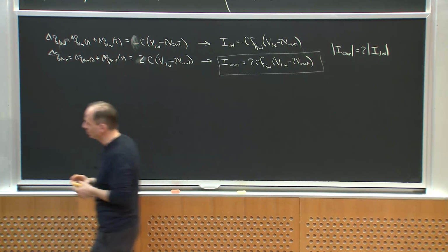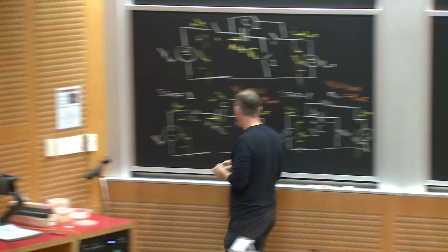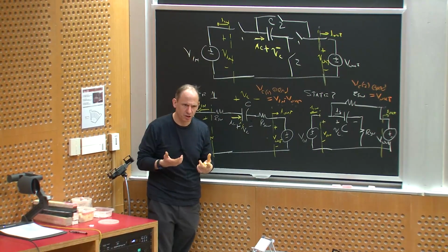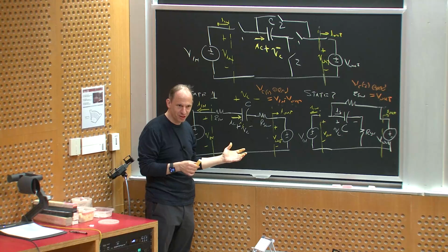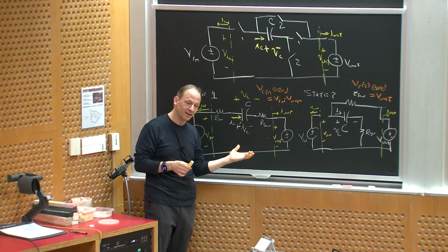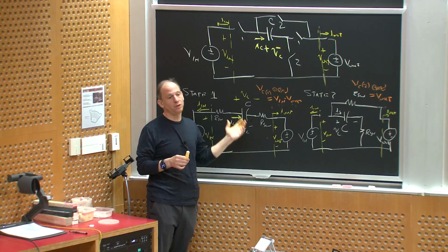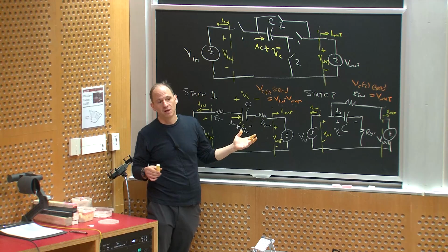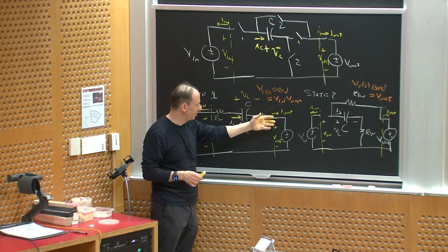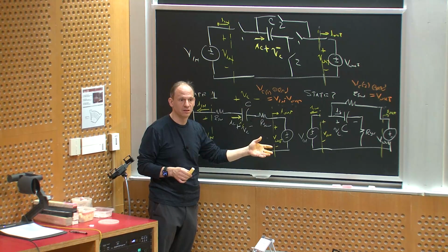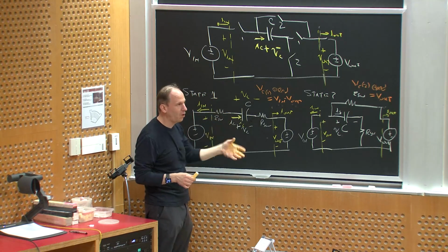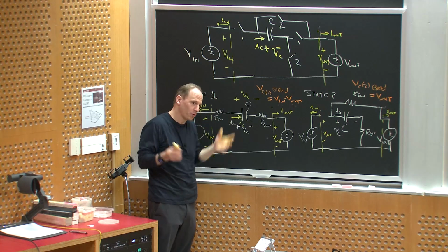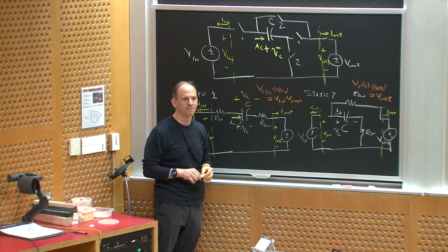All I've said is the only thing you really need to know is where the capacitor started in terms of its voltage and where it ended. If you know that, then you know how much charge went into it. So we have actually included the effect of the resistances. It's those RC charging things. If the resistances get small, I just make those RC charging times shorter. Okay? I see, thanks.